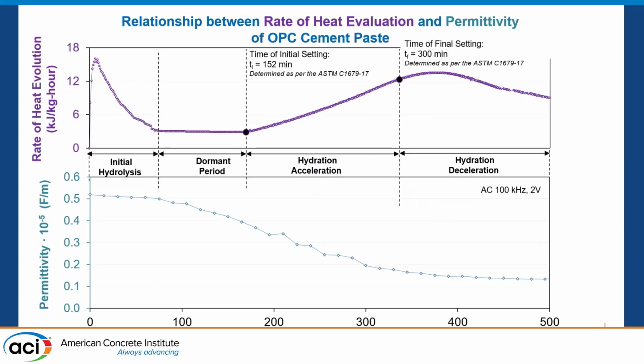In this slide, I included in the bottom part the permittivity values of the ordinary Portland cement paste during the hydration time. We conducted these measurements during hydration, and we see that permittivity starts to decrease throughout the hydration time.